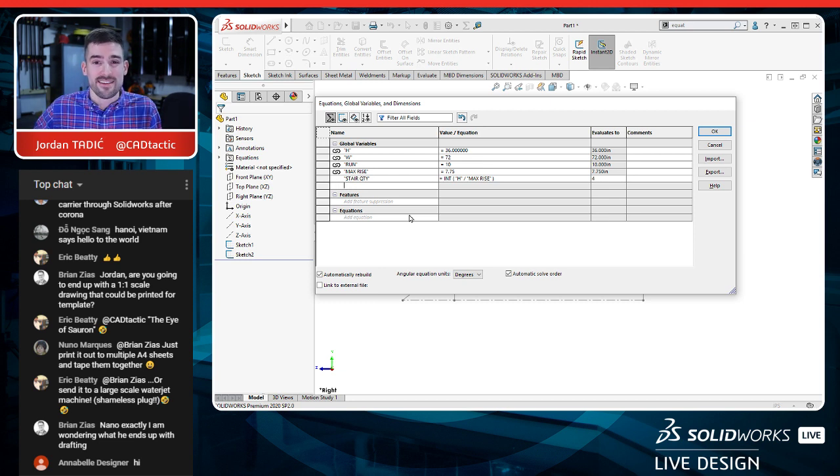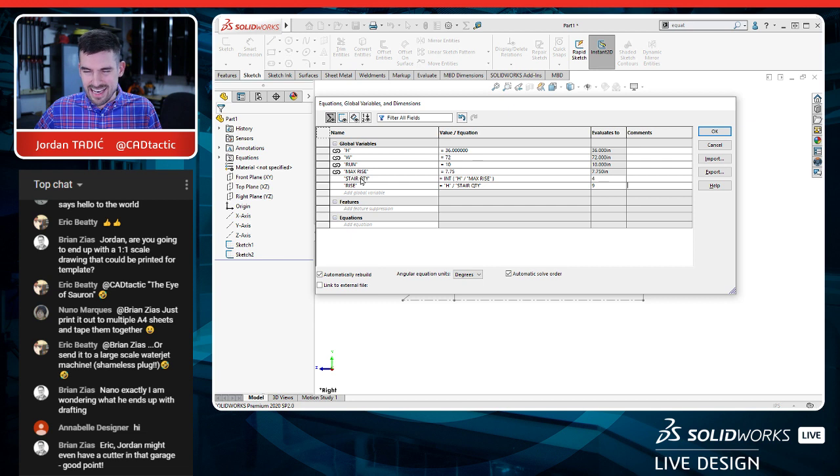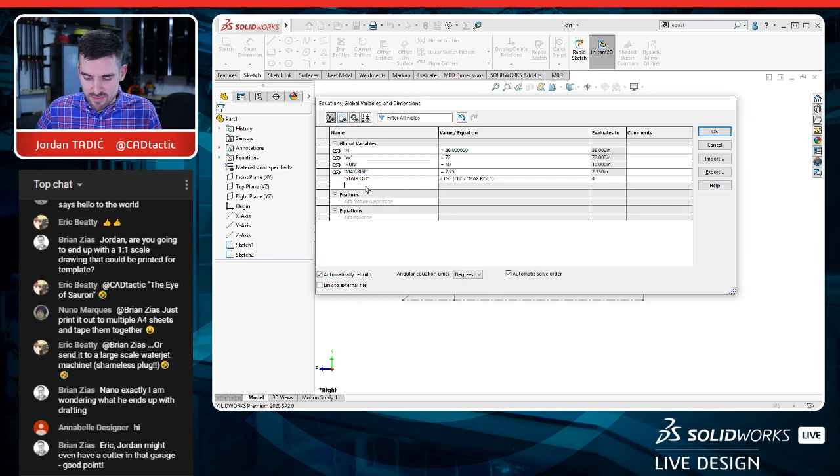Let's see what the rise is going to be with 4 steps, the actual rise. So let's see here. We're going to say the rise is going to be the height divided by the stair quantity. Enter. 9 inches. That's not right, because 9 inches is greater than our maximum rise, which is 7.75. All right, let's fix this. I'm going to delete the rise. We'll save calculating that for later. And I'm going to rename this one to stair quantity X. It's an intermediate stair quantity.